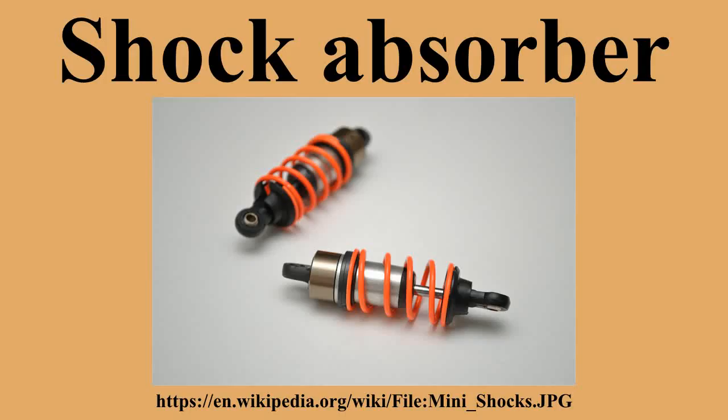The monotube shock absorber is consistently a much longer overall design than the twin tubes, making it difficult to mount in passenger cars designed for twin-tube shocks. However, unlike the twin tubes, a monotube shock can be mounted either way. It does not have any directionality. It also does not have a compression valve, whose role has been taken up by the dividing piston, and although it contains nitrogen gas, the gas in a monotube shock is under high pressure, which can actually help it to support some of the vehicle's weight, something which no other shock absorber is designed to do.